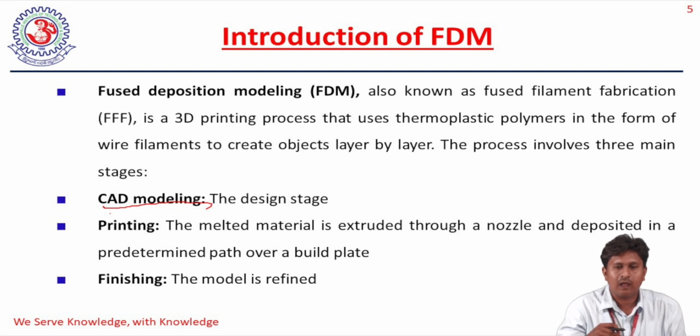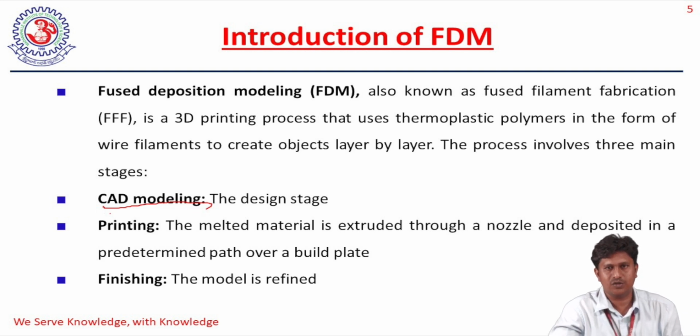So here in the slicing, first we need to slice the entire 3D model layer by layer. This will be done by using slicing software like Ultimaker Cura or Slicer. You can get these open access software through the internet, directly install it and use it.